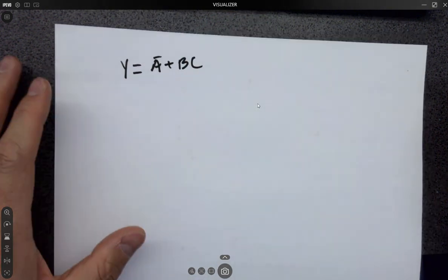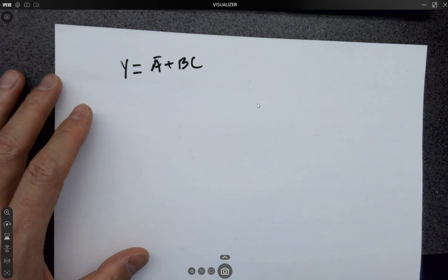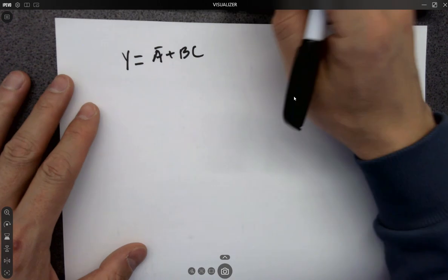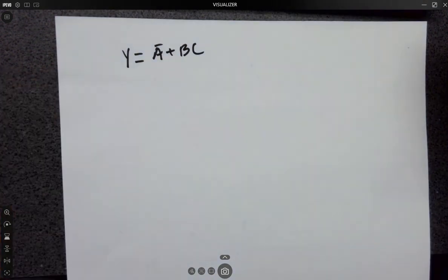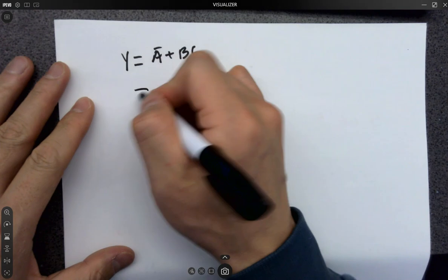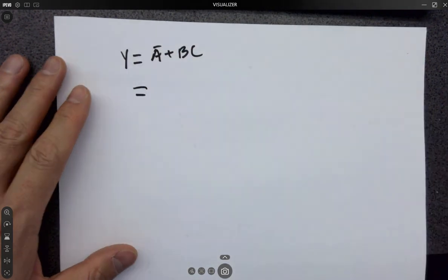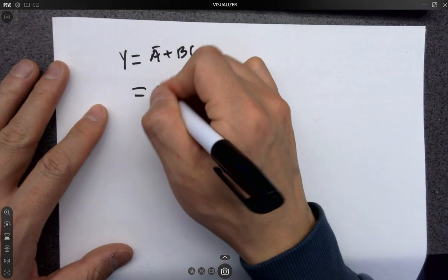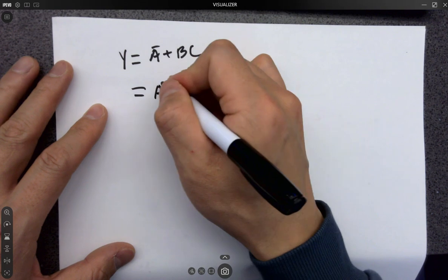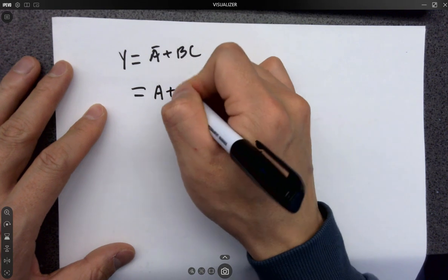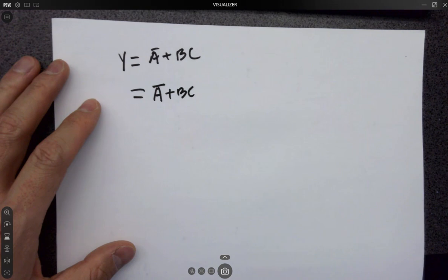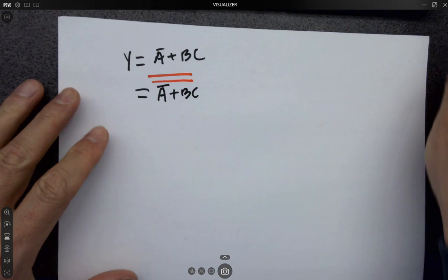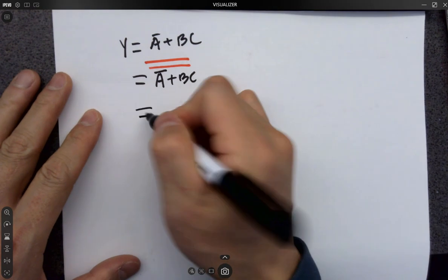It's always the NAND gates, right? But there will be some arbitrary logic expressions to ask you guys to work on. So first, you have to convert it to the AOI. Keep in mind, you have to invert. So eventually, it has to have a bar on the top. If it doesn't have a bar, we just have to add a bar on the top. If you add one bar, you change the logic. You have to add 2 bars, so it's not changing the logic. And remember De Morgan's law.